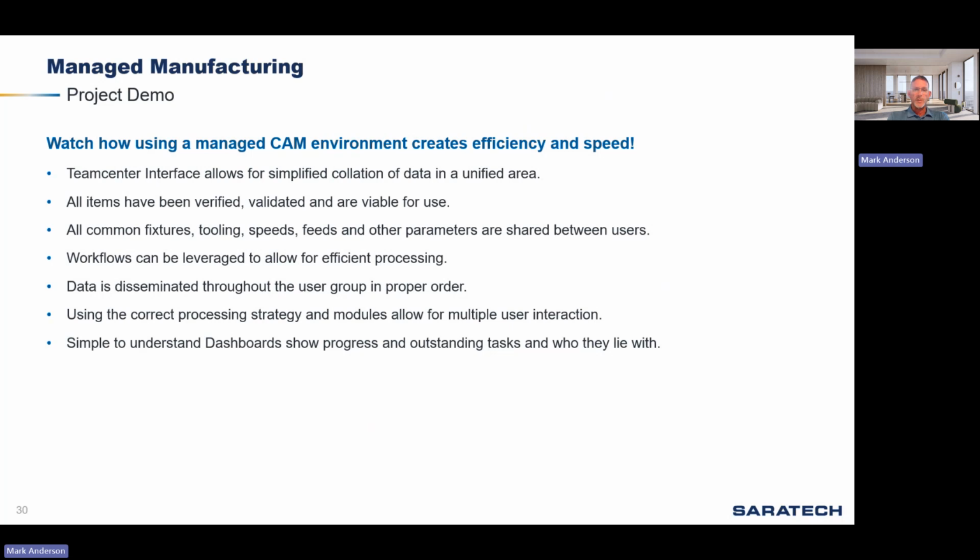So there's this module called stage modeling that allows you to physically create each individual operation representation for each individual stage. That allows for physical representation of each CAM file. So that allows for the volumetric operations within NX to be used much easier. It allows for the software to be able to understand what it's able to cut and what it's not able to cut. So you can turn the software loose on allowing it to understand and process the correct operations and correct tooling. It allows for better automation as well.